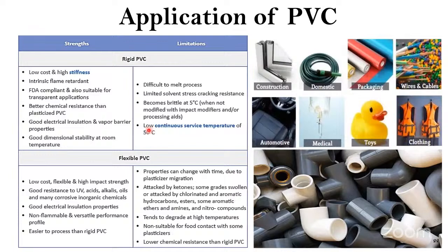Low continuous service temperature means 50 degrees Celsius is the service temperature. Service temperature means, see, this rigid PVC has many applications, but some disadvantages is that the service temperature is only 50 degrees. That is the reason we try to give them different kinds of modification.